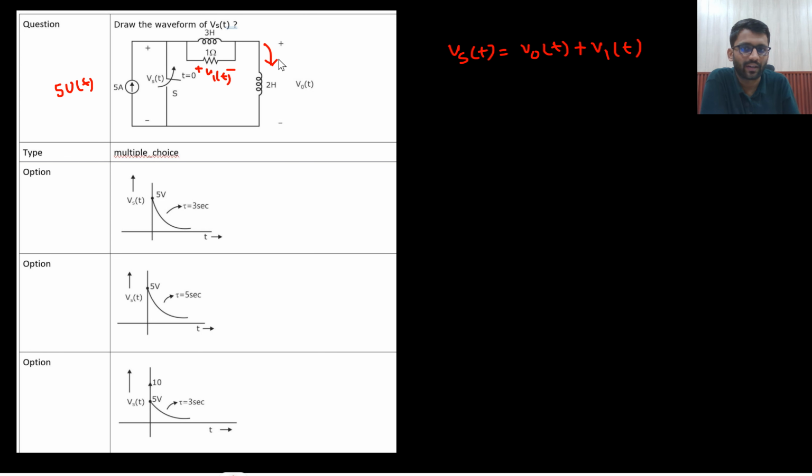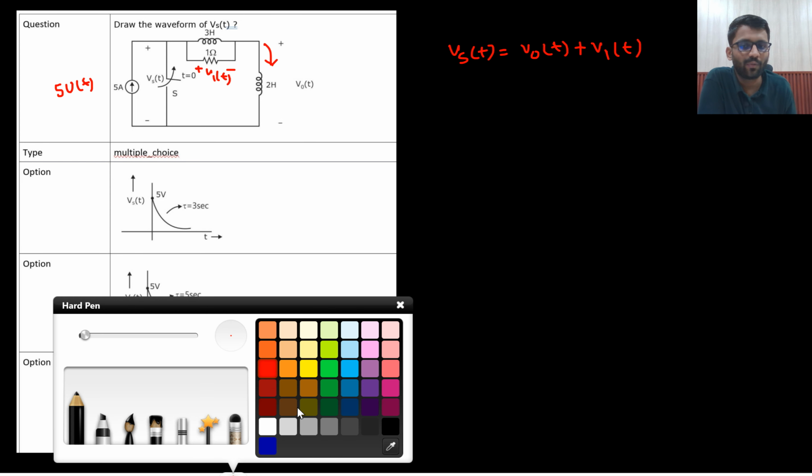This 5 ampere current. Now across this 2 Henry inductor, this is the same as the previous RC circuit. Do you remember in AIMT 1 I asked this same kind of RC circuit. There R and C was there. Here what is the change? The change is C is replaced with L, that's it. So in 2 Henry inductor there will always be 5 ampere current. Say yes or no. Always there will be 5 ampere current, right? No one can change it, because 5 ampere will flow here, it will be divided into these two, then 5 ampere will come. So always there will be 5 ampere current.